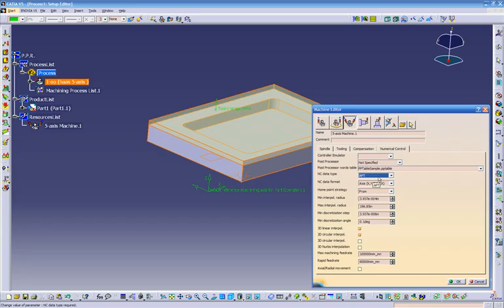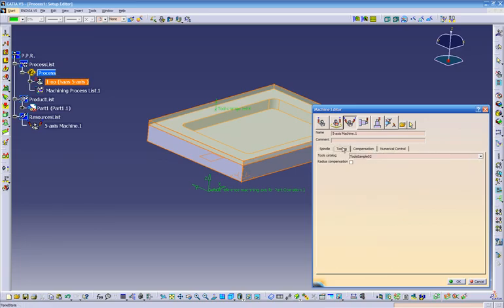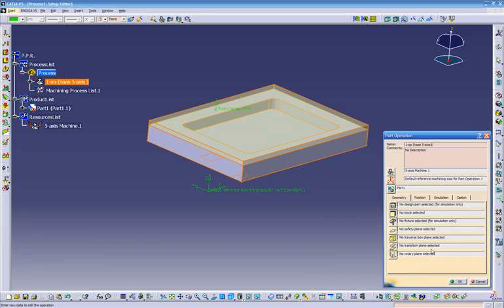And if you have a host machine, there are companies out there that will take the APT and convert it into NC or whatever your machine can read. So for now, we're going to just create APT only. Okay. So once we set all this, we're going to click OK. So we just get out of here, out of our machine.